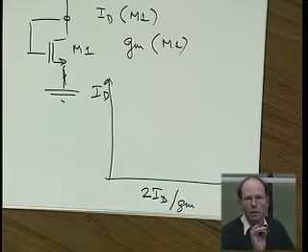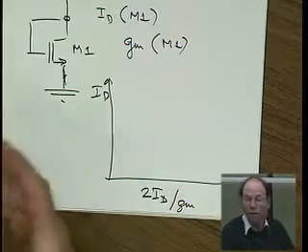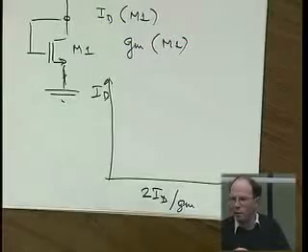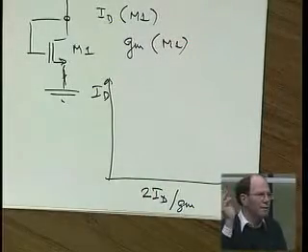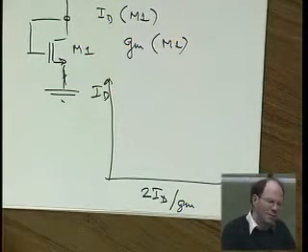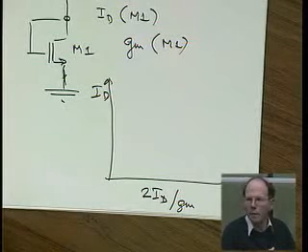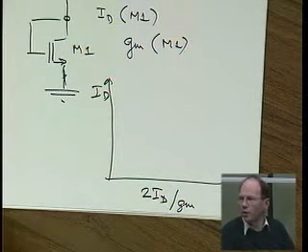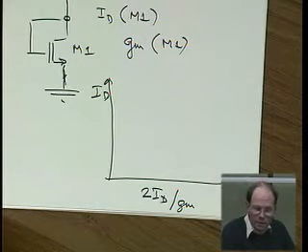And there is also one design approach that really doesn't work very well, and that is very often when we design a real chip which has to, of course, then work overall, low VDD and high temperature and slow devices and fast devices and nominal devices and so on and so forth. We start designing, setting all the parasitic capacitors to 0, using the nominal device files, using room temperature, using nominal supply voltage.